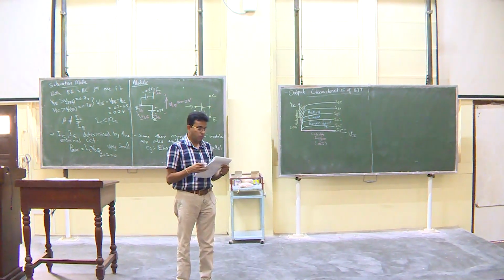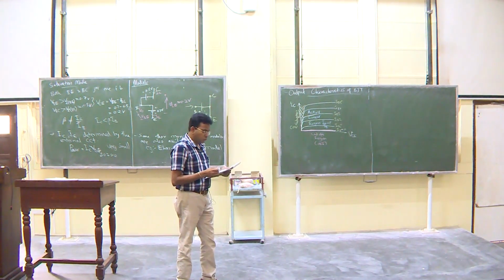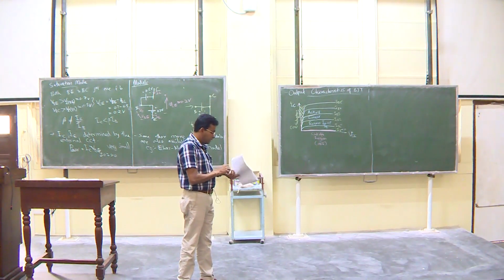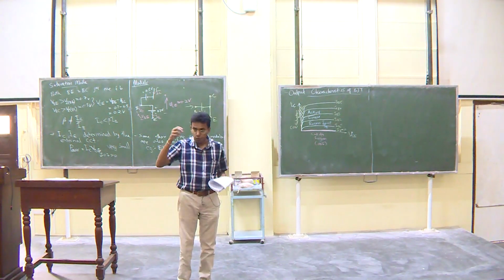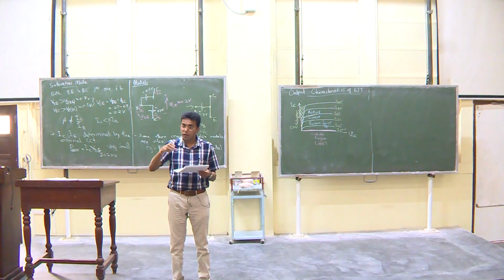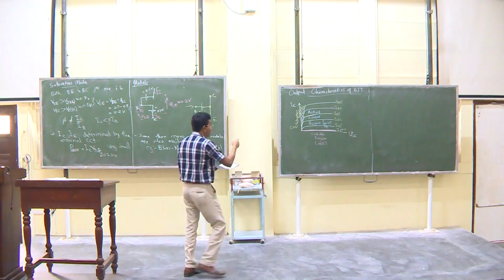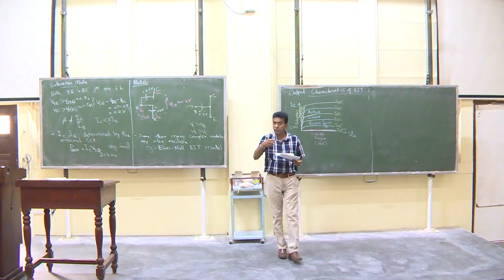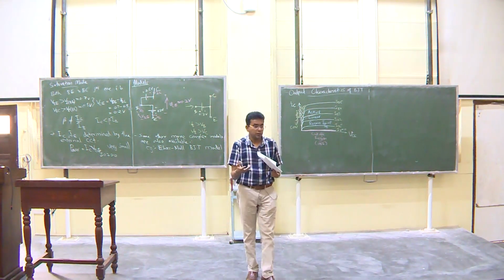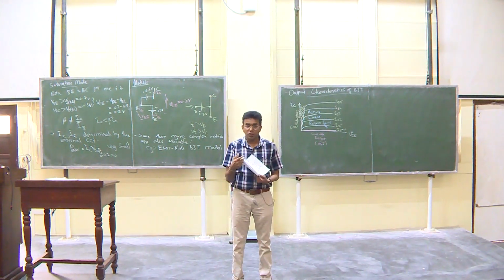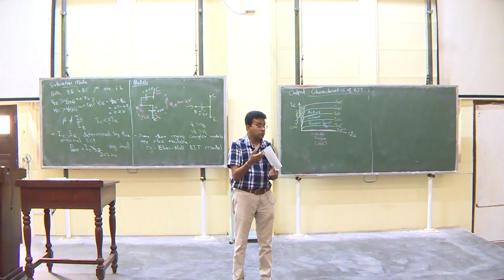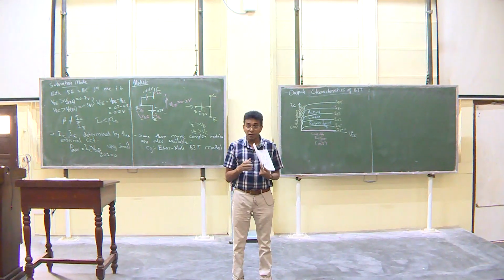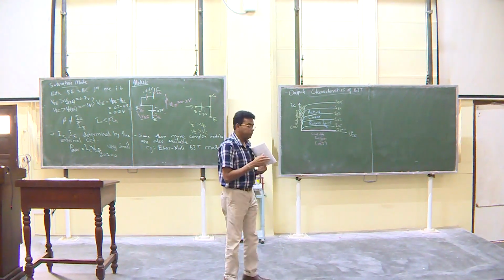This characteristic holds there. Now, though we do not typically look at it, any transistor, when you package it and when you have large currents and voltages applied, there will be VC times IC power dissipated as heat. So, when you heat things up, what will happen? That beta, I say beta will increase. What is beta?